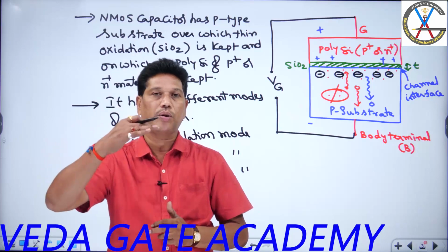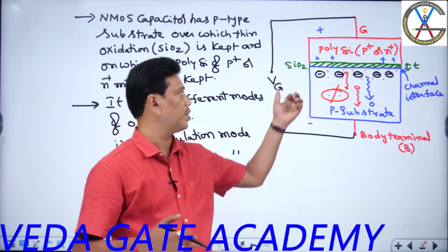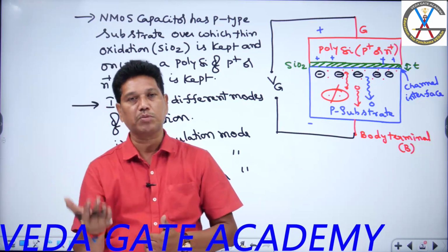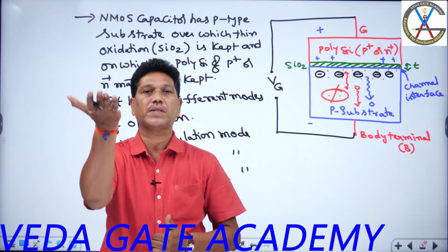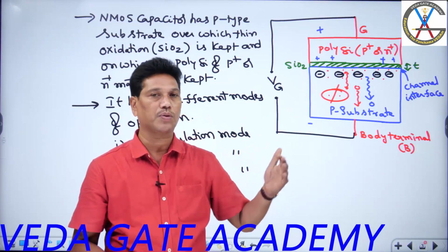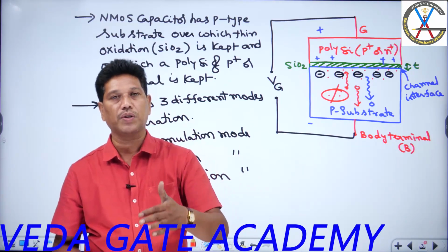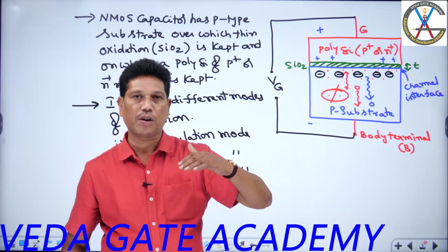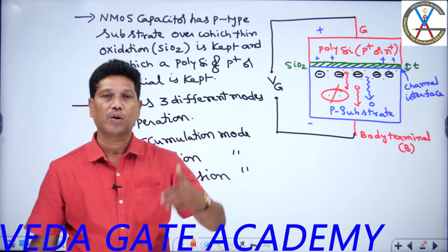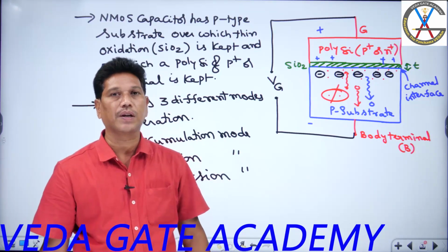As it slowly reduces, the barrier capacitance decreases. As the barrier capacitance decreases, the resultant capacitance increases. The total capacitance, you know, in the previous case was considered by COX and CD. As CD decreases, the total capacitance comes to increasing. Total capacitance comes to increasing, right?